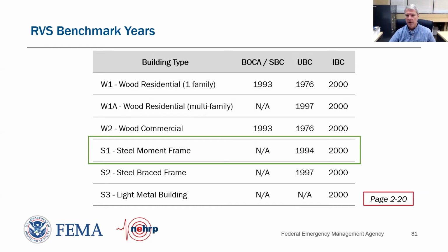And just to fill it out, if you're in the IBC, it's 2000, which is the first year the IBC came out. You would have designed to these higher seismic provisions. Therefore, you're post benchmark. You're better than the basic score, and that's what's reflective in these tables.